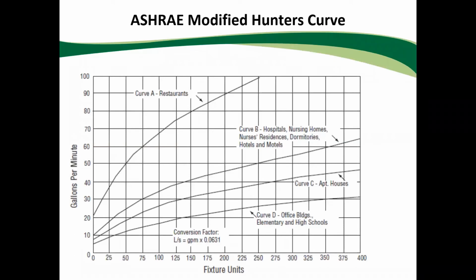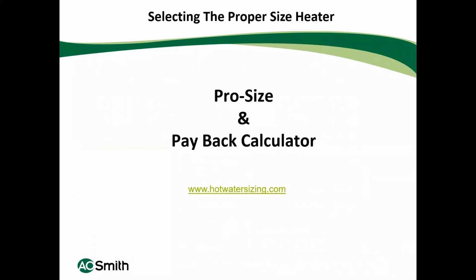So that may discourage some people, but we do build rack systems as well, so that we have up to 6 tankless water heaters on 1 rack. So the contractor carries in 1 station and hooks up 1 hot water line, 1 cold water line, 1 gas line, and he could accomplish that building. So that's basically our manual method for sizing tankless.